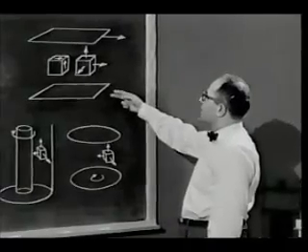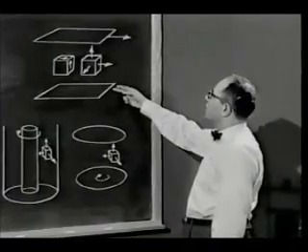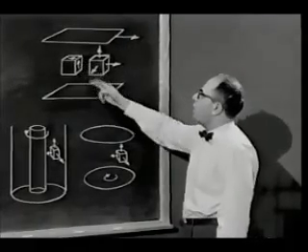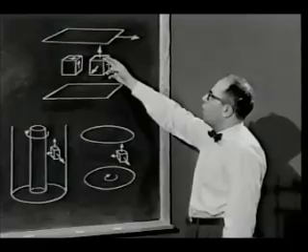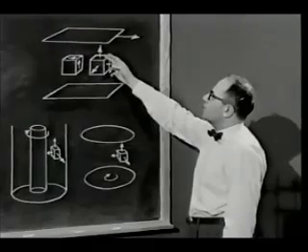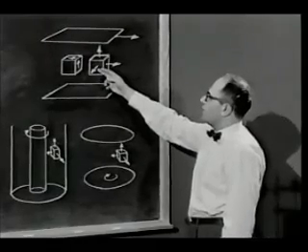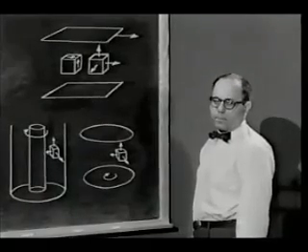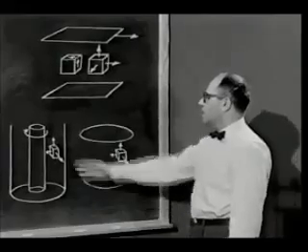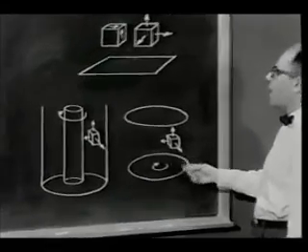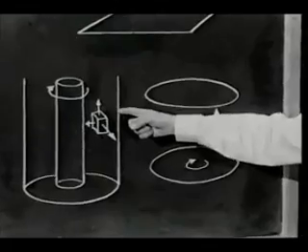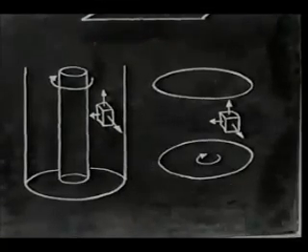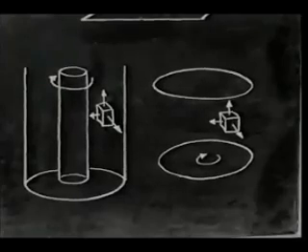This diagram represents steady, simple shearing between infinite parallel plates. In addition to the shear stresses, there are also normal stresses. For the Newtonian fluid, the normal stresses in these three directions are all the same. With nonlinearity in general, they will not be the same. We have just seen some experiments in cylindrical geometries. It is the inequality of the normal stresses on this infinitesimal volume element that gives rise to the normal stress phenomena which we have just observed.